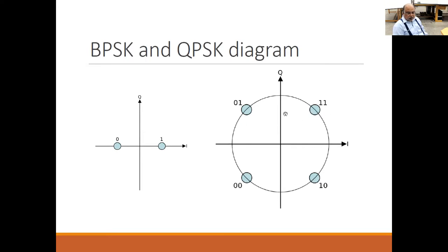All these three could be easily identified. When we were students, we remembered all these angles so well; now it feels like we're getting old and forgetting. So all these could be easily identified. Now we could assign 2 bits to each signal. If I had a signal which was 45-degree out of phase, I would say I am receiving 1 1. If it was 135-degree out of phase I would say I am receiving 0 1.